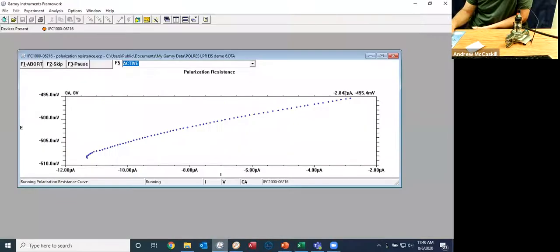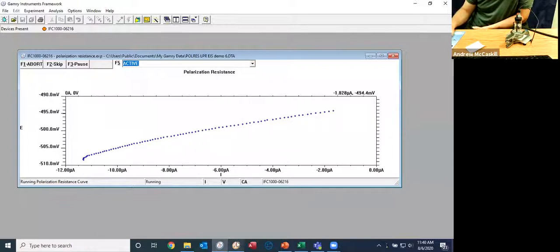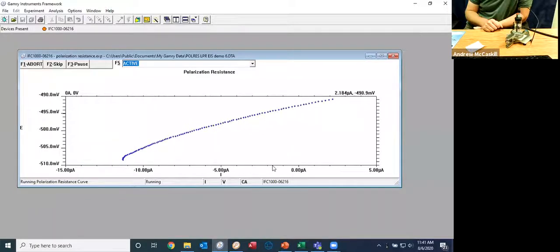Let's see what's going on with our LPR measurement. Here's something interesting. During the first LPR experiment, the currents were much, much higher than what we're seeing right here. So the currents themselves have come down. That tells me that the initial blast of corrosion that we saw when I first put the cell together is slowing down a bit and reaching what I'll call a point of equilibrium, or maybe steady state's a better term for that. But these are all little things in experiments that happen.